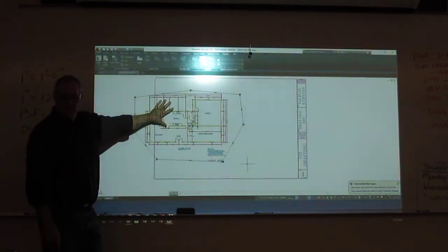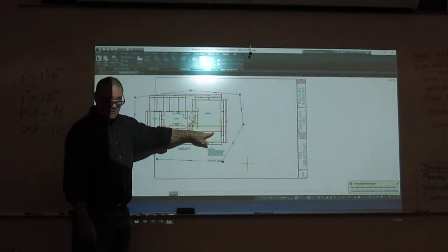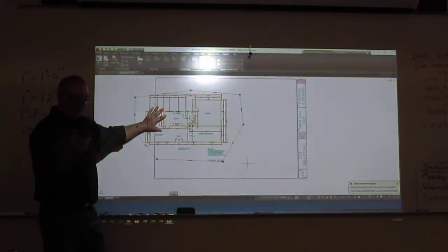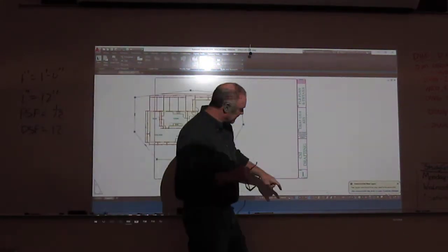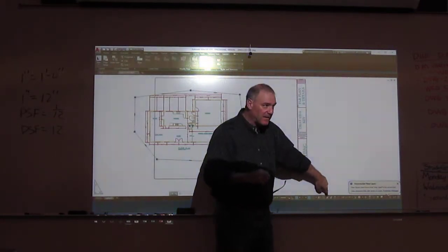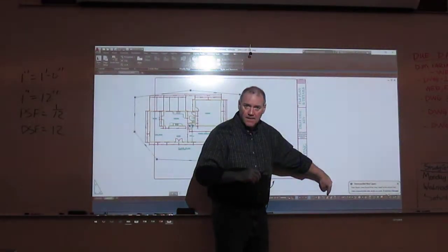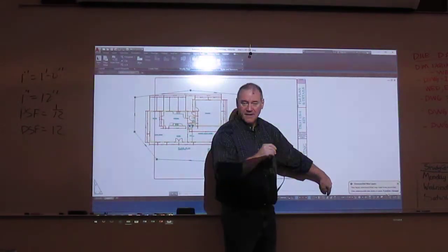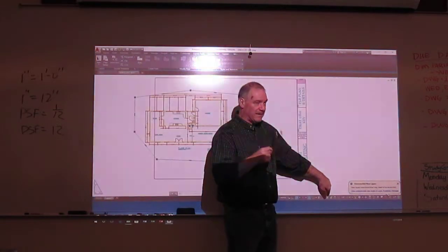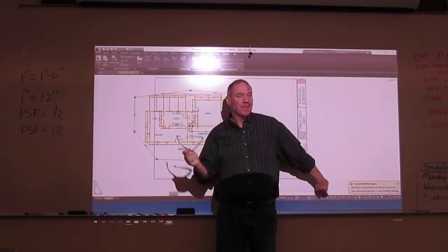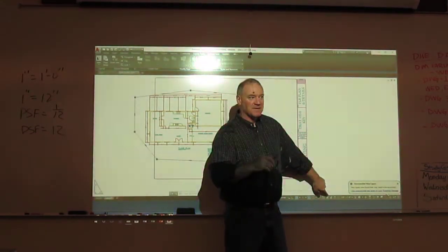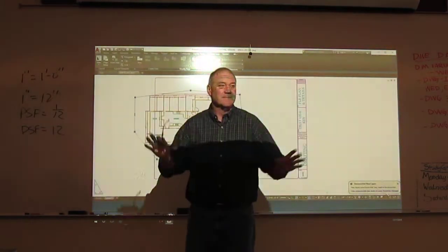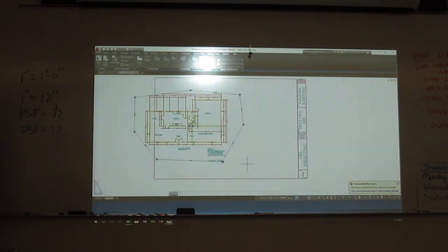Now, does anybody not have any dimensions that show up? Because you will have times, and I think some of you have had this problem on other drawings, where you've got dimensions in model space and they're not showing up here. That's because of the first scale item right down here on your annotation scale. That's the variable that's turned off, and it's meant to not display any annotative objects that don't match the scale of this viewport. If you've got an object with no annotation on it, it won't display it. So just click that button and it shows everything, regardless of the annotation scale.